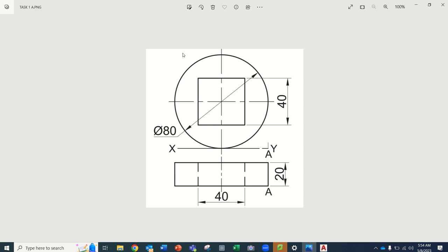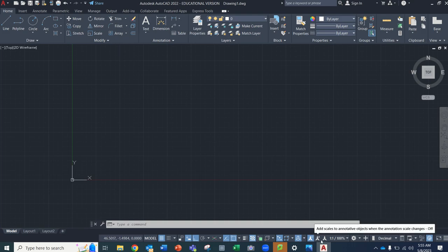down the middle. So we're going to open up AutoCAD and get ourselves set up and ready so that we can draw within the isometric framework that CAD gives us. We're going to open AutoCAD and it should look something like this for you. What I do is I press Fn F7 or F7, depending on what type of laptop you have, and that should take the grid away in the background. As you see, I don't like to work with the grid. I like to just have a clear background.